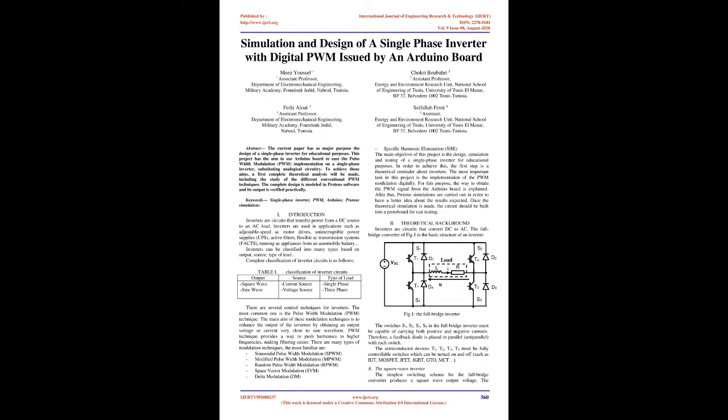There are many types of modulation techniques. The most familiar are Sinusoidal pulse width modulation, SPWM. Modified pulse width modulation, MPWM. Random pulse width modulation, RPWM. Space vector modulation, SVM. Delta modulation, DM. Specific harmonic elimination, SHE. The main objective of this project is the design, simulation, and testing of a single-phase inverter